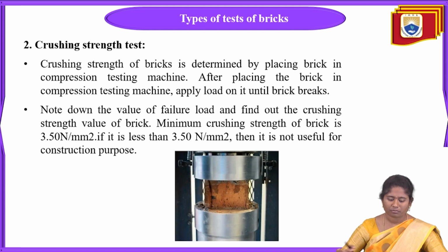Okay, the next test is the crushing test. In this test, the crushing strength of the brick can be determined by placing the brick under the compression testing machine.